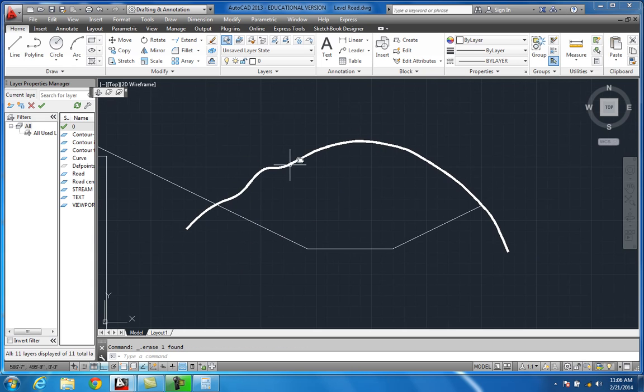So again, this is the mountain. This is our angle of repose that we're going to cut out, and this is going over 2 and up 1. This is a 2 to 1 angle of repose. So all this stuff will be cut out, and this is what we'll be left with. And the reason that you do this is because when you're driving on this road, this is again the profile shot. We're driving down the road here.